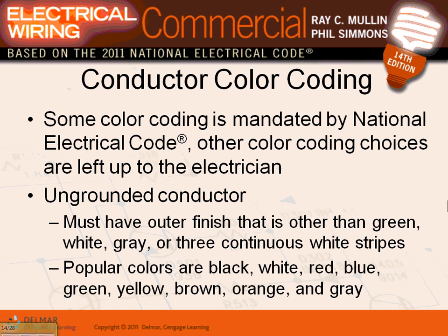This is a three-phase, 20 amp circuit. Remember how we did the math, depending on the size, up to probably 17 fixtures you can feed from each one of these. 17 times 3 will give you how many fixtures you can feed from these 5 wires I'm carrying in my hand.